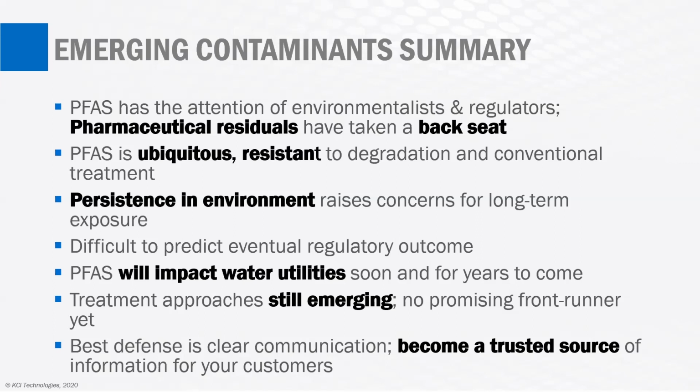But in general, people are talking about that 1100 degrees C number for removal. And so if your process is getting up to that level, then I would feel confident that you're going to be able to impact PFAS. For lower temperatures than that, I suspect it's going to be a continuum. There will probably be some that it's effective for and others that are not. So again, that's going to be a subject for future research.